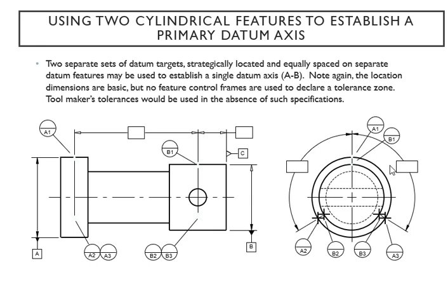So therefore we can combine them, and if you have a single control frame, you can put it in the same cell, yeah. Of course, in this example, we don't have the frame, yes. So we have no idea where the tolerance zone is. Anyway, we do have the basic dimension that you can trace, yeah, all the way to your datum targets.